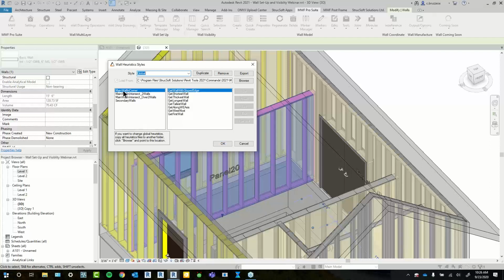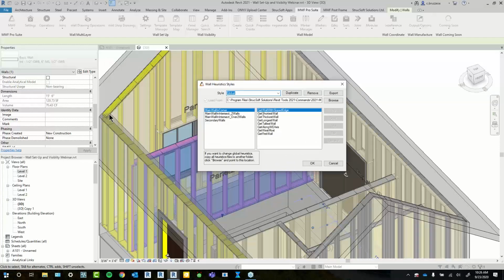So a good example over here, if you've got walls in a corner, we'll take any wall with a sloped edge as the main wall first. So this one will be taken as the main wall. It's the one that's actually going to be lengthened. But after that, we always do take the shortest wall as the main wall to keep continuous. So if ever you do want to change this priority list, move it up and down,